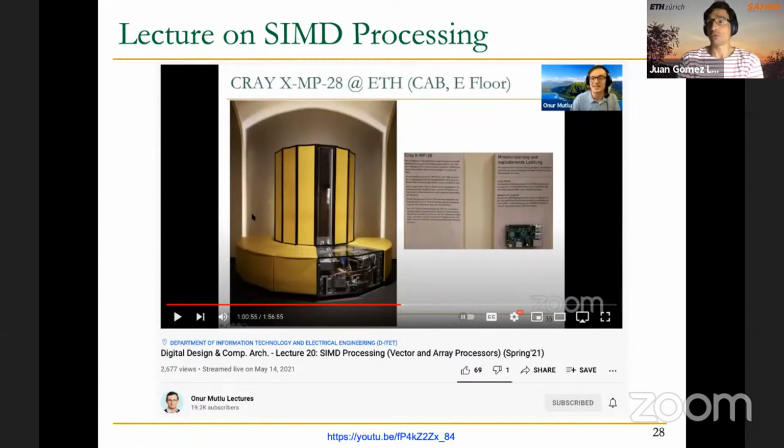So if we have 32 banks, for example, this means that the size of each bank is 2 kilobytes. And there are some proposals, for example, to reconfigure the number of banks depending on the characteristics of your program, and this way reduce the bank conflicts for that particular program. That will require some extra hardware. But there are many proposals about this, and we will mention some of them in future lectures.